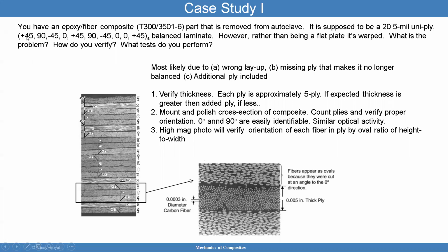But what is important is that what you see here is a stacking sequence. And what I mean with stacking sequence is this tells you how the composite is built. So the first number is plus 45, and that goes against the tool. So if I call this the tool, here at the bottom, the metal tooling, for example, then that plus 45 goes right there at the bottom. Then I put a 90-degree ply above, then a minus 45, and so forth.